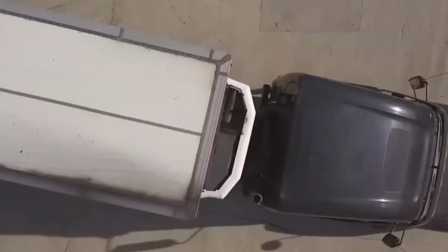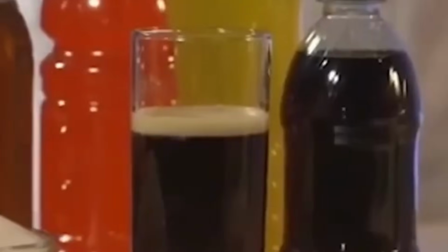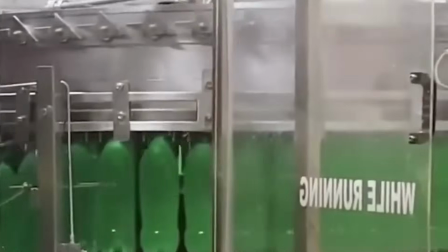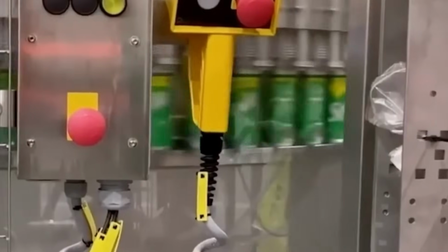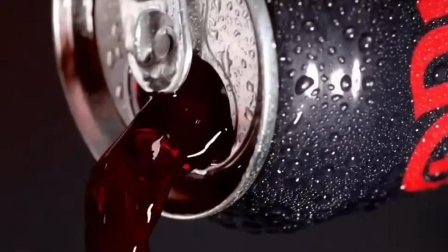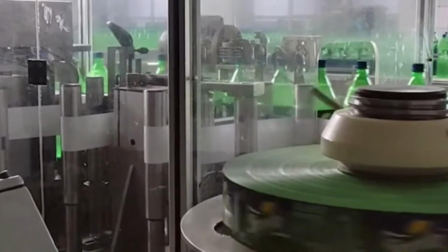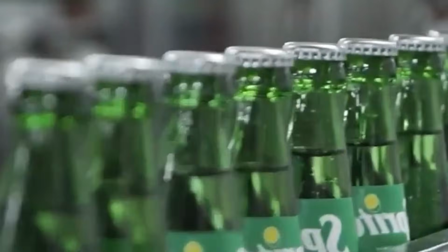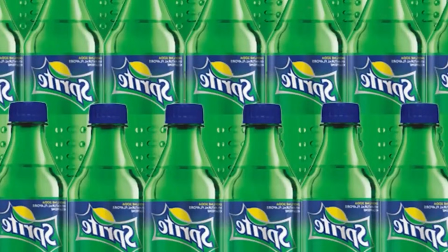The mixture is kept under continuous motion with variable speed impellers that prevent stratification. Once all components are incorporated, the syrup is heated rapidly in a tubular heat exchanger, held at pasteurization temperature for a brief duration, and then chilled through a countercurrent cooling system.